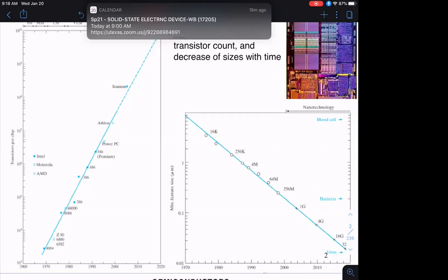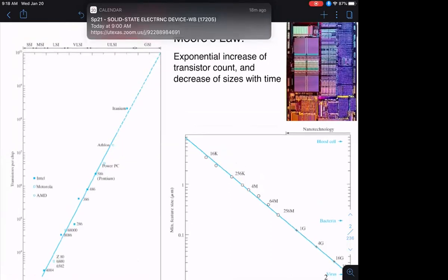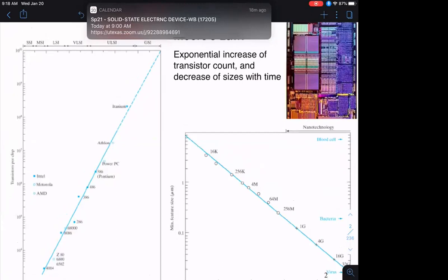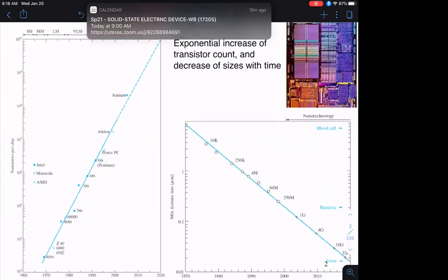And then depending on the number of transistors, people have given the technology different names. If there's only a few hundred transistors, it's called SSI, meaning small scale integration. Then a few thousand, medium scale, large scale, very large scale. Then up to a few 100,000, it was ultra large scale. And then by the time you went to 1 billion transistors or so, that's called giga scale. Giga means 1 billion or more. And that's kind of where we are. So you're talking about 1 billion to several billion. And the joke is, the next era of IC technology will be called RLSI, ridiculously large scale integration.